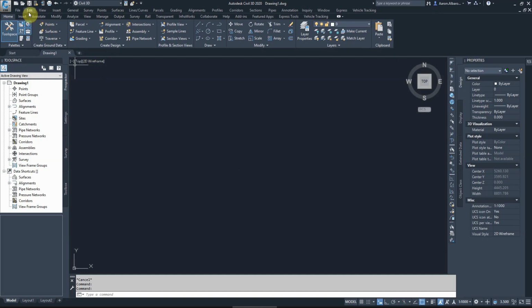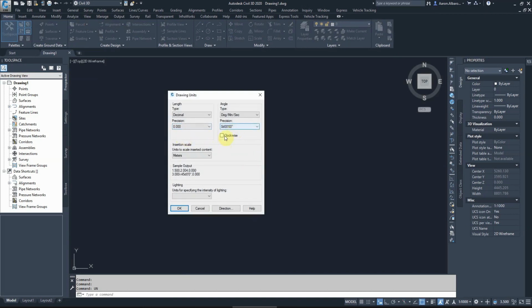So how do we do that? First of all, I need to insert that PDF into the drawing here. Before I do all of that, very important, check your units. You press enter, and that will show you your units. Our units are meters for civil work. Not like structural design, where we use millimeters. In civil work, our main unit for length is meters.